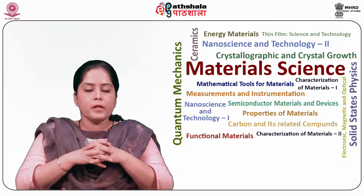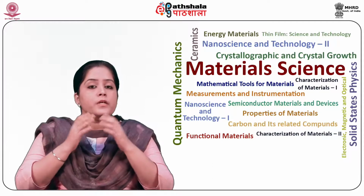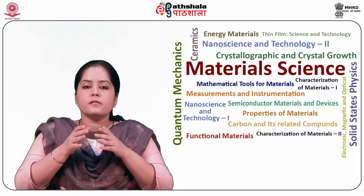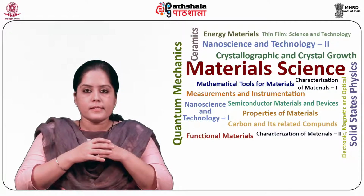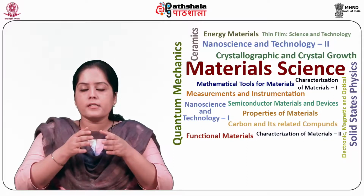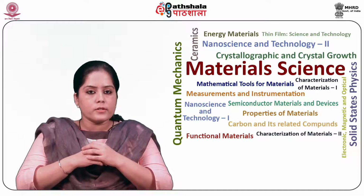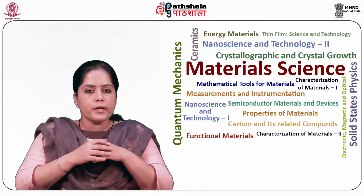Applications of ALD. ALD can be used in various applications including high-K gate oxides, storage capacitor dielectrics, pinhole-free passivation layers for OLEDs and polymers, passivation of crystal silicon solar cells, high aspect ratio diffusion barriers for copper interconnects, adhesion layers, organic semiconductors, highly conformal coatings for microfluidic and MEMS applications, other nanotechnology and nanoelectronic applications, coating of nanoporous structures, fuel cells, for example single metal coatings for catalyst layers, biomems.